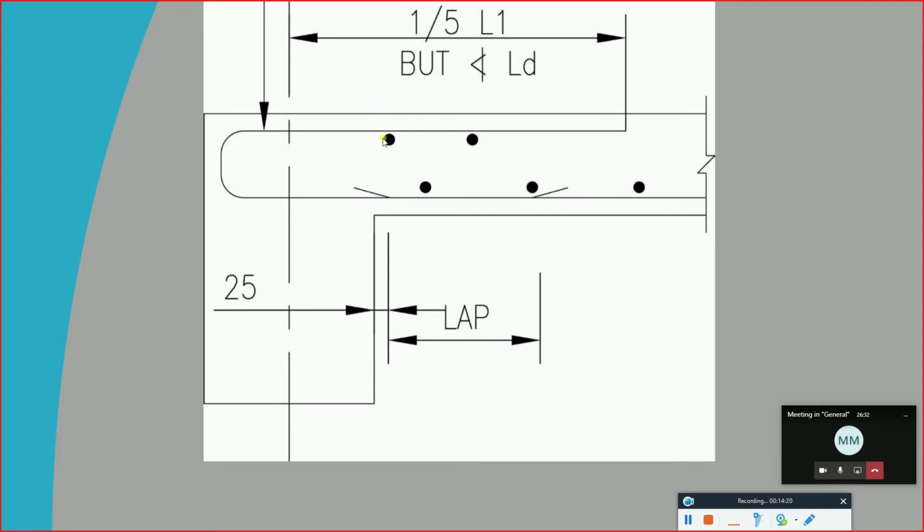Okay, and then the circular reinforcement here is on the other side. So these are representing the long side, or the y direction reinforcement. So here this is x reinforcement for the bottom, this is y reinforcement for the bottom, this is x reinforcement for the top, this is y reinforcement for the top. X refers to short, y refers to long.